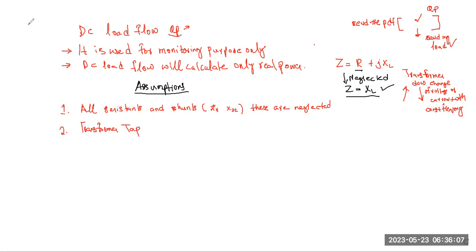Suppose you have a transformer, a step up transformer. This side is your step down side. You feed 120, and this is a 1:2 transformer. Suppose you don't know the other value, so you write 120 divided by x is equal to 1 by 2, so x would be equal to 240.